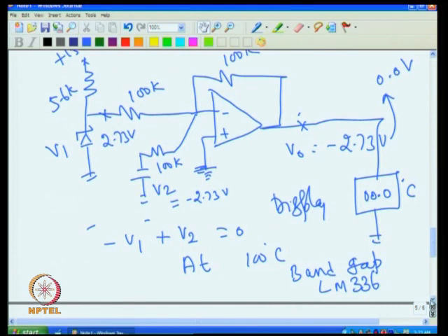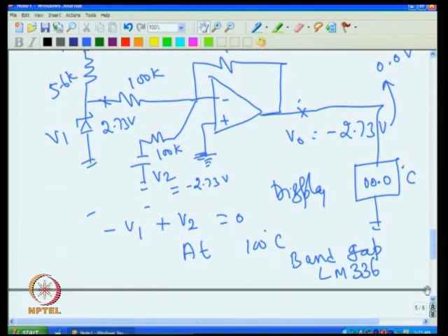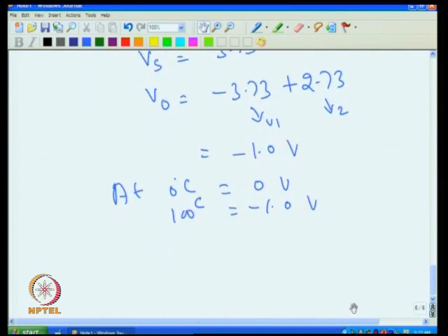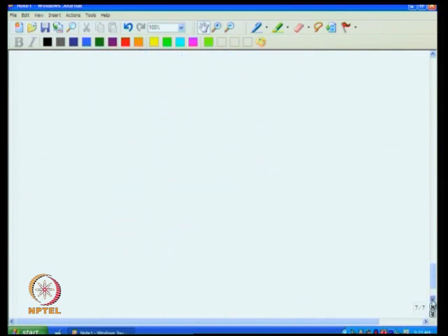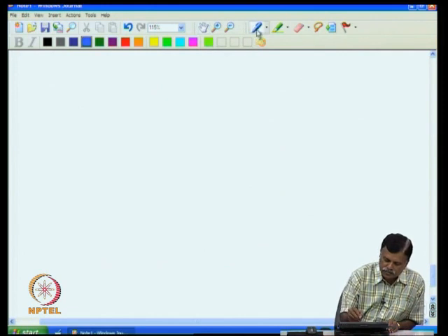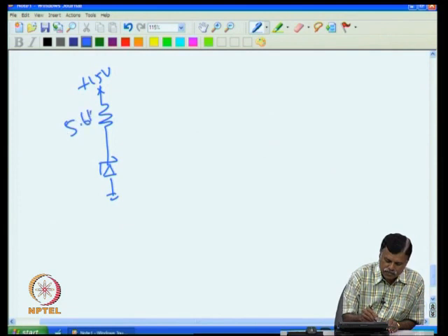So what happens if I connect that Zener, because I have no other go, I have to use only that 2.5 volt Zener. So if I take the 2.5 volt Zener, then with that how will I design the circuit? So what I can do would be, I can take our temperature sensor. We had 5.6 K here, and this is LM335, that is the sensor.